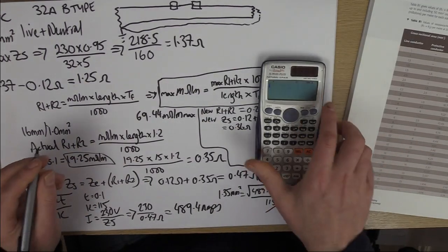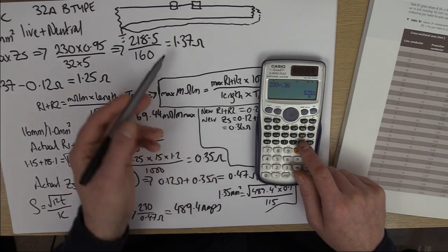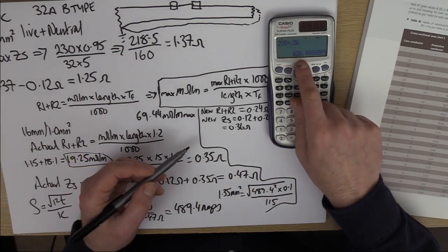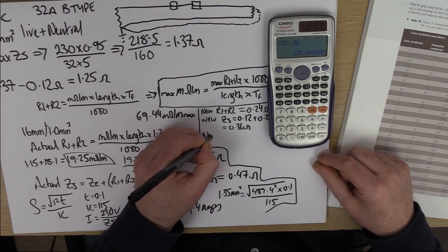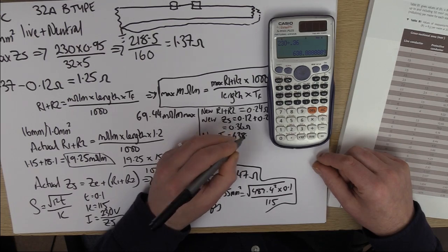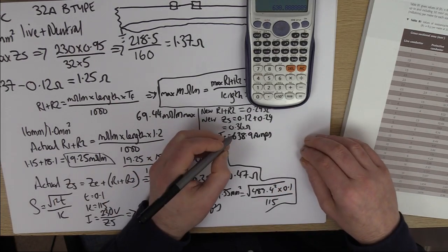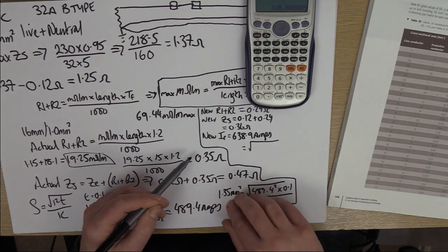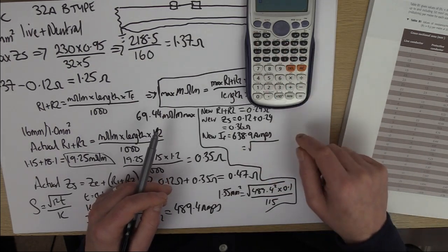So that means new fault current, 0.36 clearly still complies. So that fault current's now gone up to 638.9 amps. And then we'd have to put that back into the adiabatic now to make sure this is still okay, maybe, because this might mean that the 1.5 is not big enough. So let's try it.